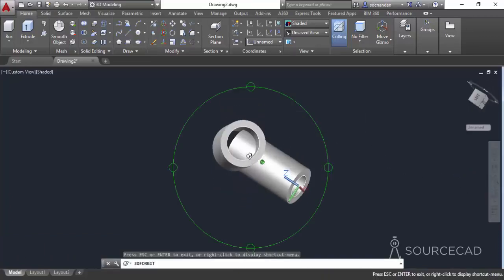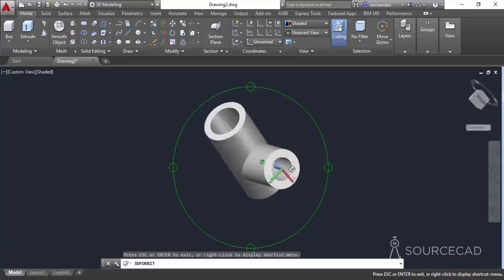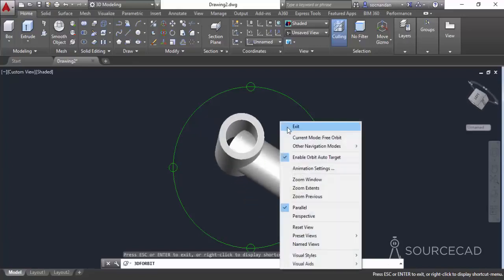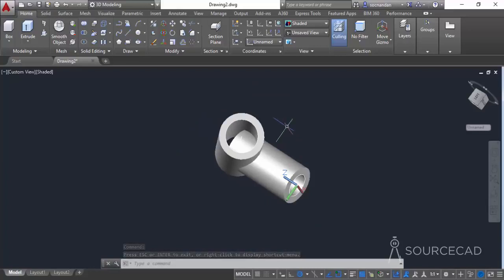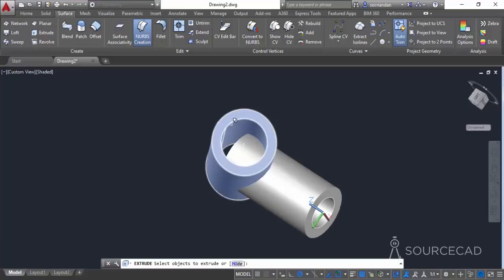Let's look inside these drawings, and here we have this portion which we don't need, and also we have here this closed portion that is not required. So we need to trim both of these sections. For trimming, we can use slice command, but before using slice, let's make two surfaces. So go to surface, select extrude and click on this internal circle. So when you hover your cursor over this circle, you'll notice on this tooltip this overlapping square icon.